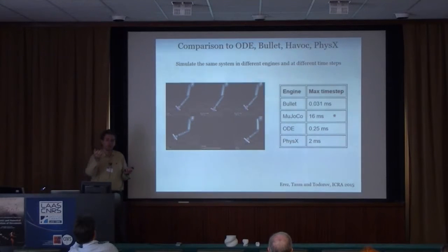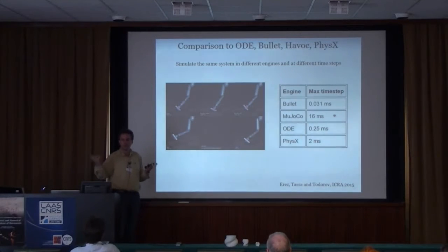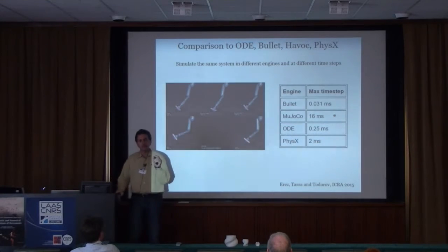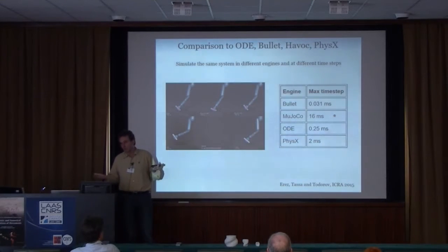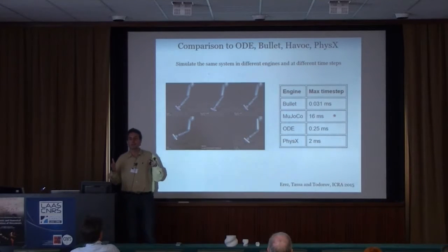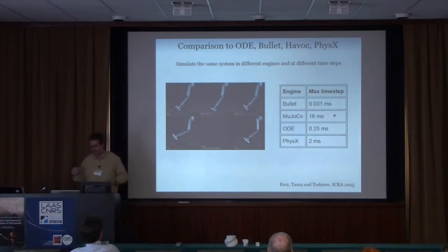So we know we're applying enough force and there is enough friction so that a real hand would keep the object there. And as with almost every example of numerical integration, if you make the time step really, really small, things are going to be accurate. But you don't want to make it too small because it's going to take you forever to compute anything. So the question is, how big can you make a time step before things break down?